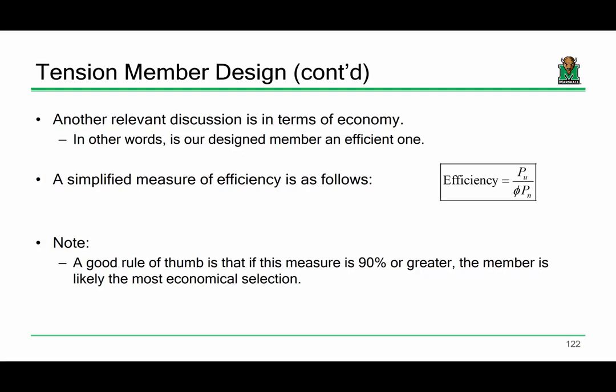But keep in mind, you're not using raw loads. You're taking that live load and you're bumping it up 60%. You're taking that dead load and you're bumping it up 20%. Think net section fracture. We took the capacity and we multiplied it by 0.75. So there's a lot of safety factors built into that. So it's like once your safety factors are built into it, at what point do you say you can cut it off? So, honestly, I'd say go with it.